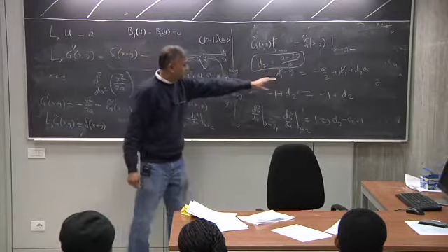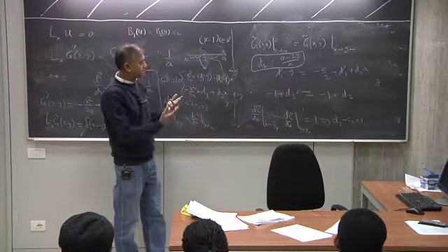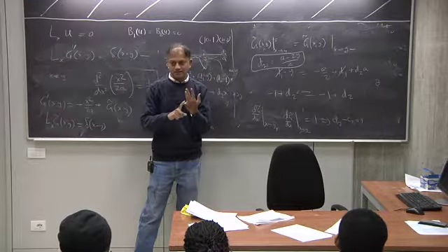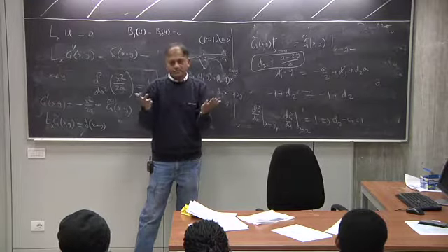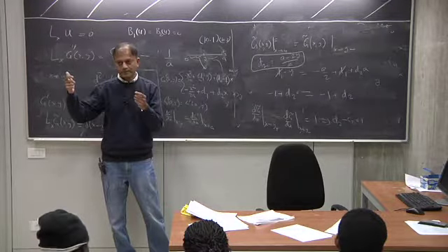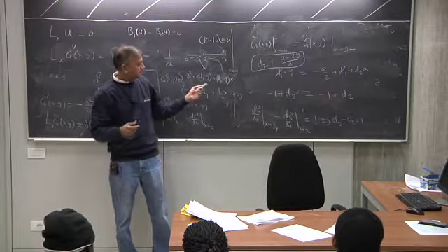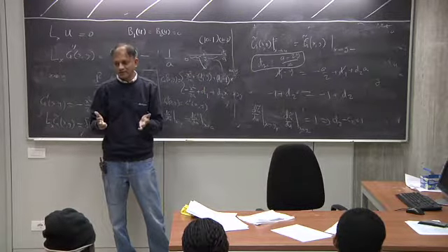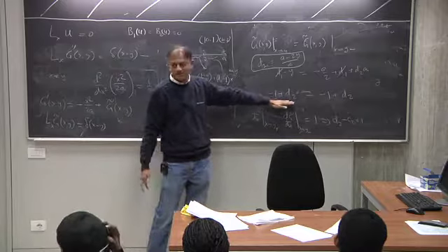Okay. So this is always the case. To begin with you have 4 conditions: the continuity condition, the discontinuity condition, and the 2 boundary conditions. So normally you would say with these 4 conditions I should be able to fix C1, C2, D1 and D2, right? But here we find that out of these 4 conditions only 3 give you non-trivial information. 1 condition was automatically satisfied.